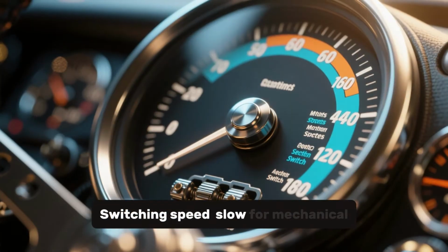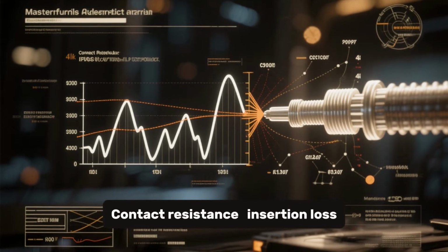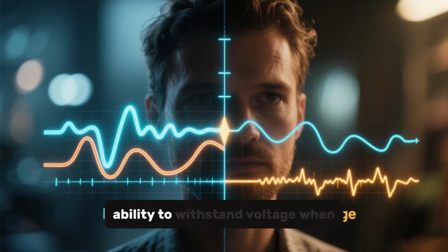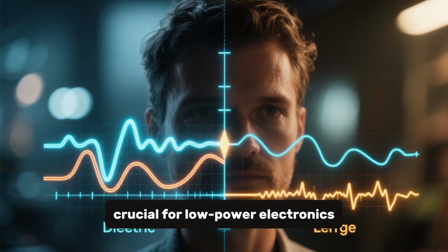Switching speed, slow for mechanical, very fast for semiconductor switches. Contact resistance/insertion loss, important for power heating or signal attenuation. Isolation and dielectric strength, ability to withstand voltage when open. Leakage current and off-state resistance, crucial for low-power electronics.